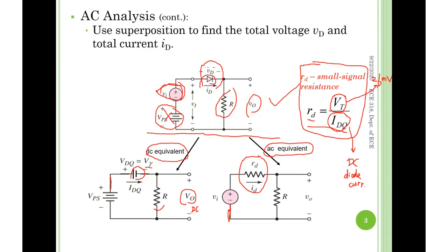In the transistor circuit, the same idea. In transistor, AC small signal model is in terms of DC result. So DC analysis always goes first. All right, very good. Okay, I gave you this first. This goes first. This one follows. Here, once again, is emphasizing DC analysis model is a voltage supply, V gamma. Small signal model is RD, resistor.